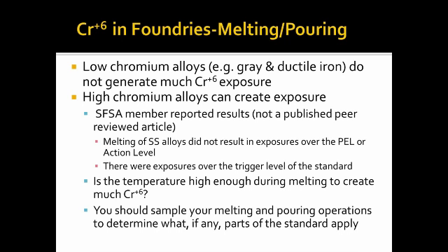There were some member-reported results from SFSA, which is another foundry association. It's not a peer-reviewed article, but they polled members and asked them to supply information about their sampling data. And the sampling data that was provided, again, not peer-reviewed, certainly not a scientific study at all, indicated that the melting of what they referred to as stainless steel alloys didn't result in exposures over the PEL or action level. There were exposures over that trigger level, so certain parts of the standard do apply. However, they didn't find much over the PEL and action level.